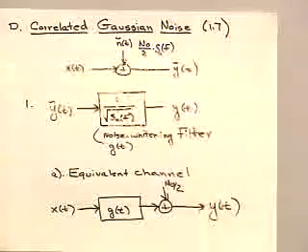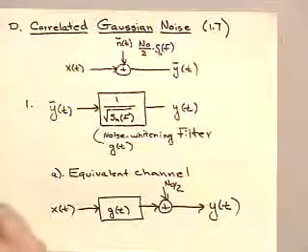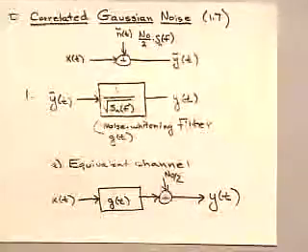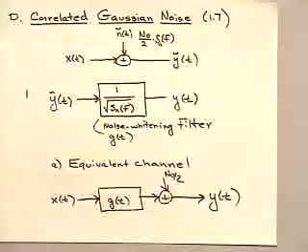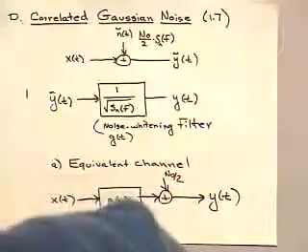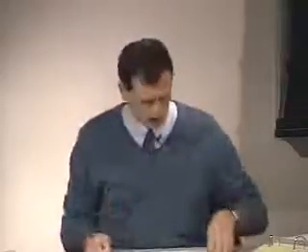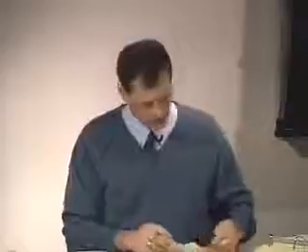If I had notches in a channel, okay, which are caused maybe by that multipath fading we're talking about, that's going to be the same as if I had very narrow band noise, like some kind of sinusoidal interference at some frequency. They're going to produce similar degrading effects on a channel. So you can get intuition. You know about ISI, you know about noise. You can kind of use this and go back and forth between the two.